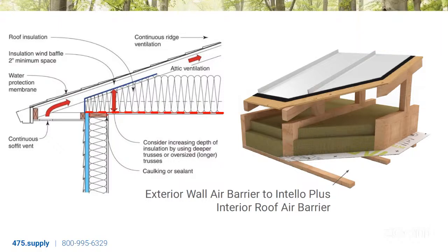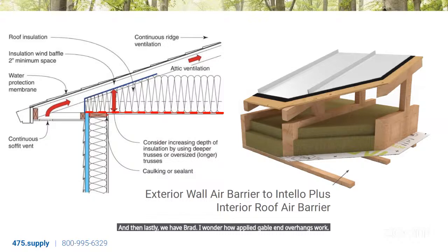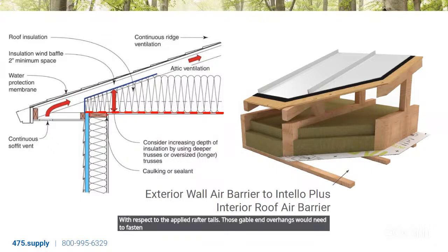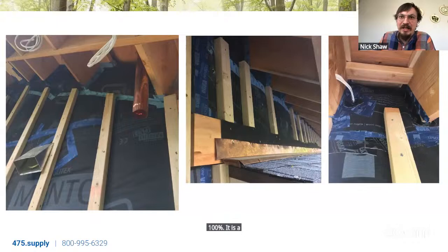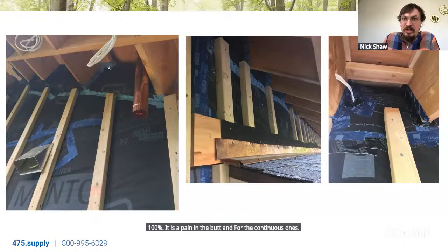And then lastly, we have Brad. I wonder how applied gable end overhangs work with respect to the applied rafter tails / vents. Those gable end overhangs would need to fasten perpendicular to the applied rafter tail vents, which would obstruct venting to the roof at those ends. 100%. It is a pain in the butt. And for the continuous ones, you're just taping around it.